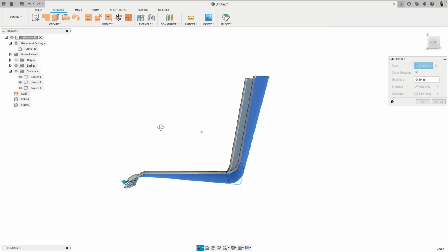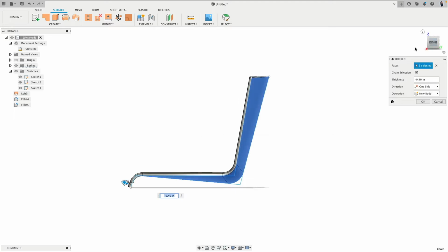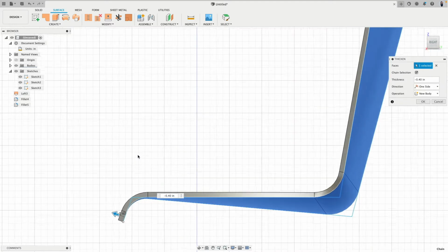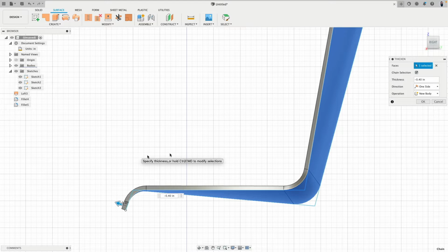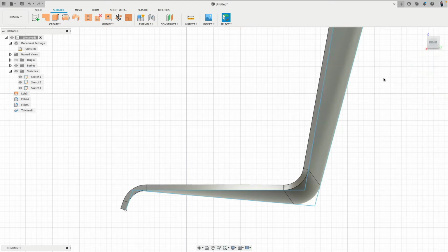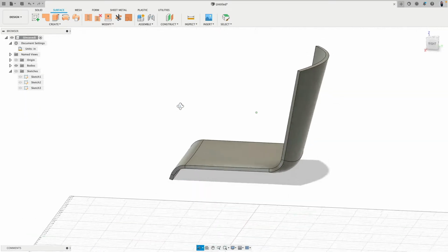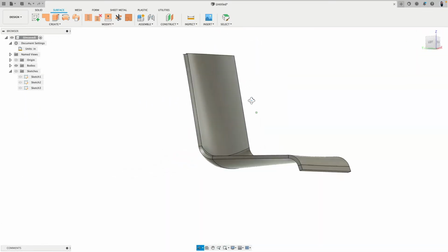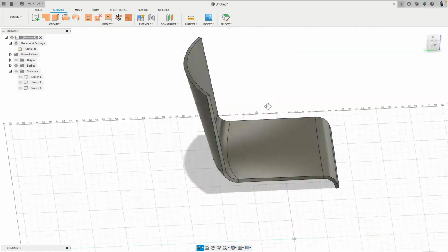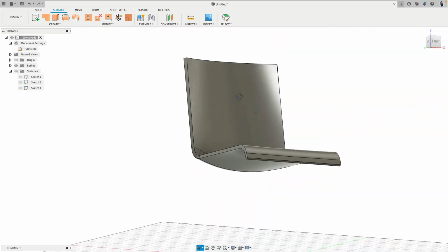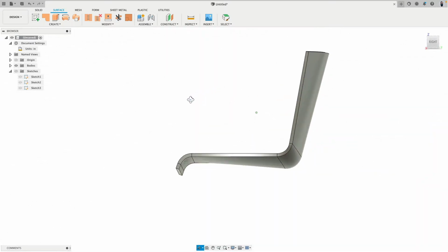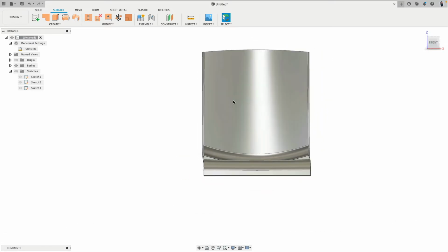And I thicken this to the outside, maybe 1/2 inch. Okay, very good. These commands all I select and dissolve. So when we rotate around, we actually have created a pretty well working shell for a plastic chair.